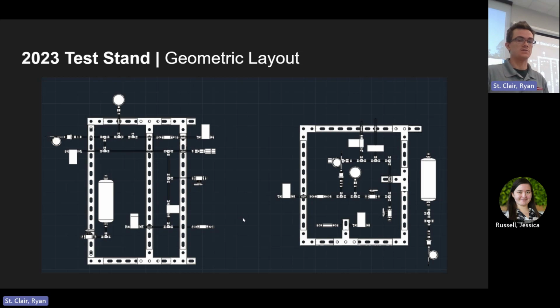You can imagine your rocket engine right here. And when you have very little oxidizer in your environment, that will immediately extinguish the flame, because you're getting rid of one of the components of the fire triangle. That's basically why we chose to do this bypass like that. You can see this is where the burst disc would be. This is a ball valve here. This is that solenoid valve that we use to click on and off to immediately relieve pressure remotely. And we have a gauge here and transducers here.